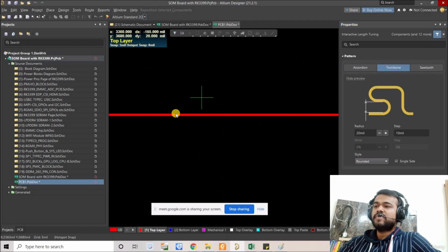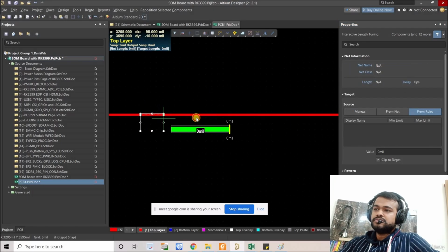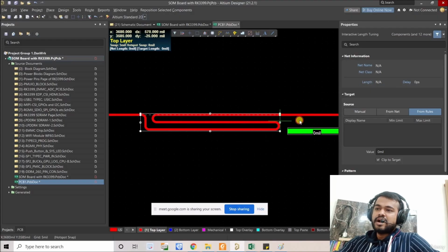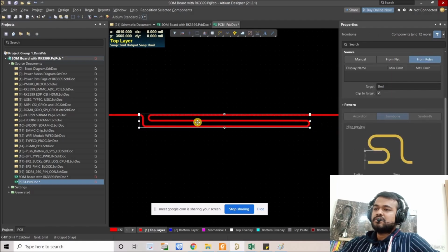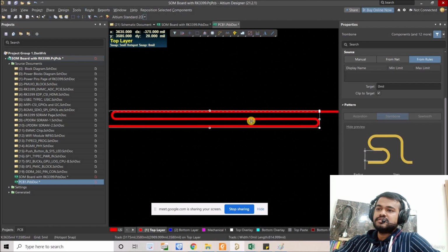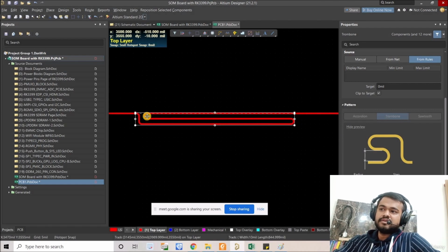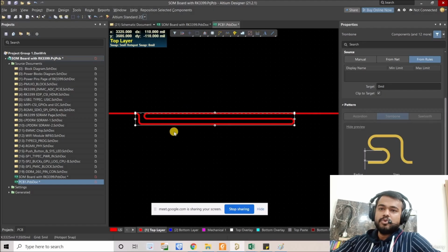So for example, I have very little space and I have to length match those. You can see we are routing just 3 tracks in parallel, okay, and you can see that in a very small area we have routed so much length, right? Almost thrice the length, right? So if one section is x, this is x, then this total length will be almost 3x, right?